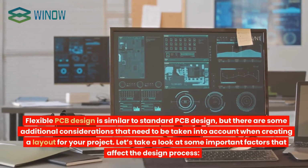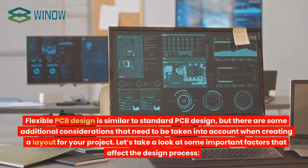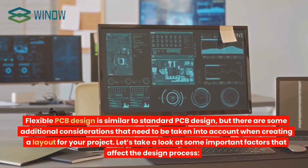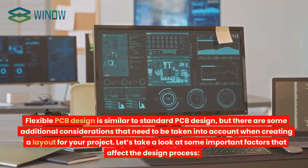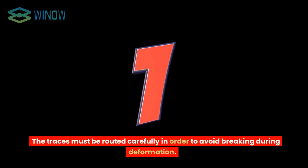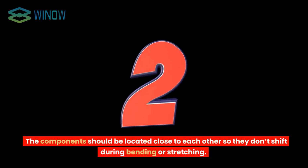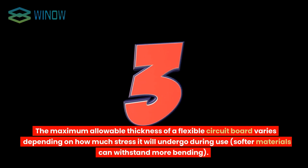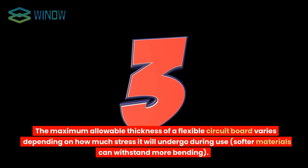Flexible PCB design is similar to standard PCB design, but there are some additional considerations that need to be taken into account when creating a layout for your project. Let's take a look at some important factors that affect the design process. The traces must be routed carefully in order to avoid breaking during deformation. The components should be located close to each other so they don't shift during bending or stretching. The maximum allowable thickness of a flexible circuit board varies depending on how much stress it will undergo during use. Softer materials can withstand more bending.